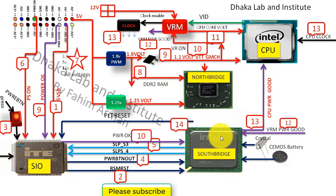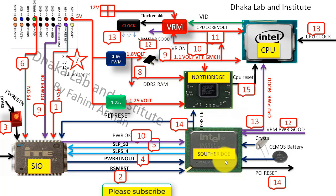Then the South Bridge will pass PLT reset to IO, and it will also pass PLT reset to the North Bridge. It is a very important signal. If this signal is okay, then you can see that everything is fine. Then the South Bridge will provide PCI reset, and the North Bridge also provides CPU reset to the CPU.